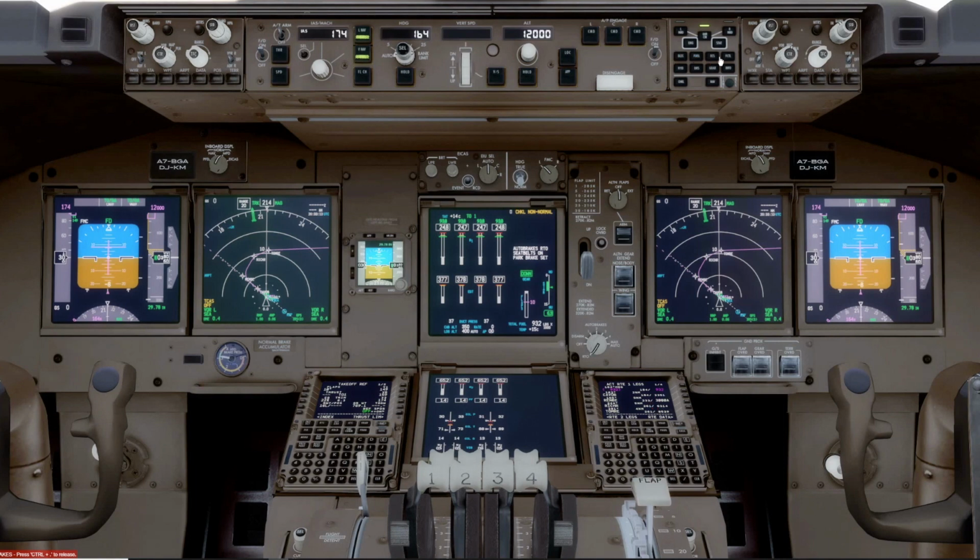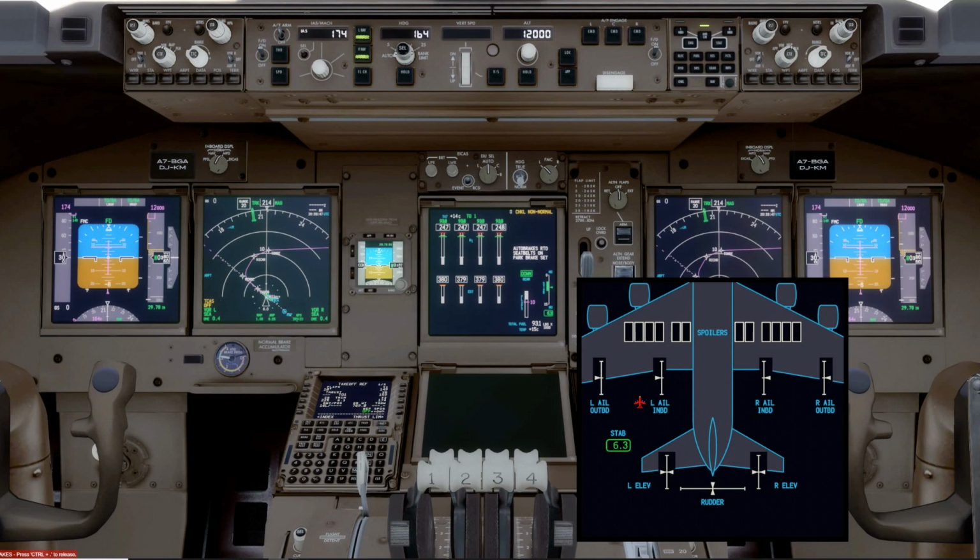And just prior to that, I probably came up here and turned on the flight controls, and then the captain would do the flight control check. And so he'd go right aileron and check for 2 up, 2 down in the Dash 8, and the spoilers on the right side, and then 2 left, 2 right, proper direction, full movement, and again spoilers on the right, on the left side are displayed, and then 4 down on the elevator, neutral, 4 up on the elevator. You notice the Dash 8 shows all 4 surfaces instead of just 2.